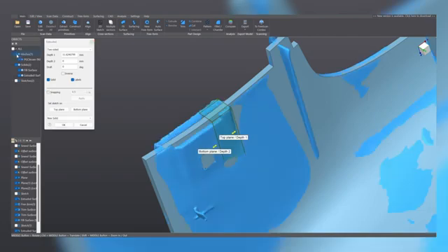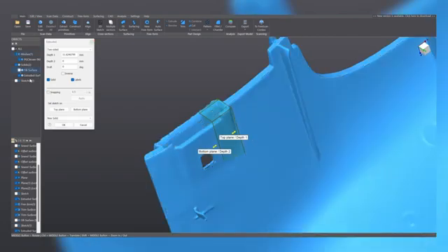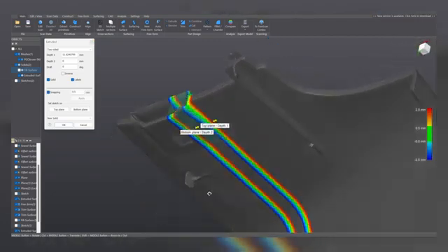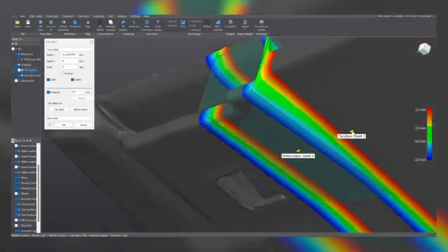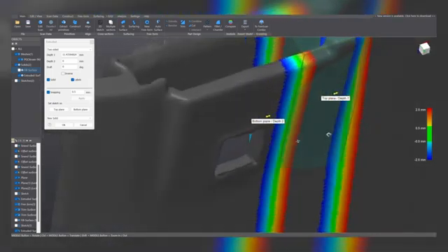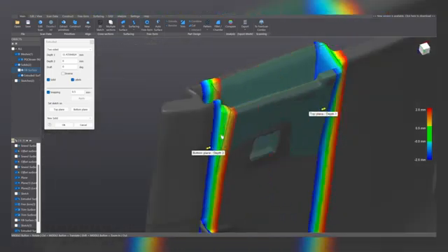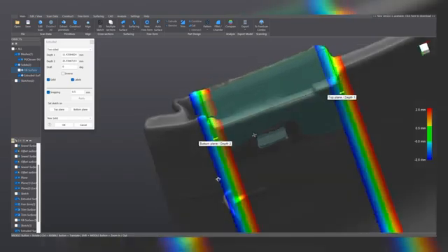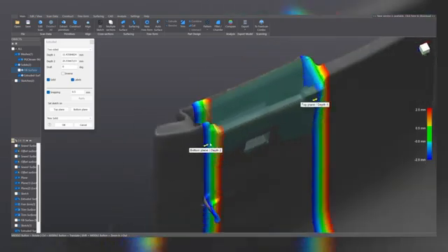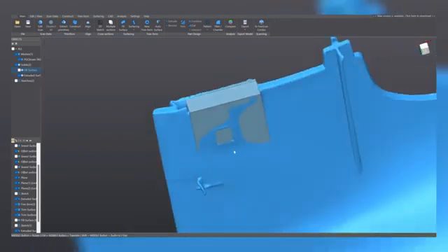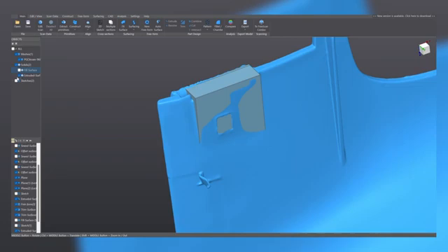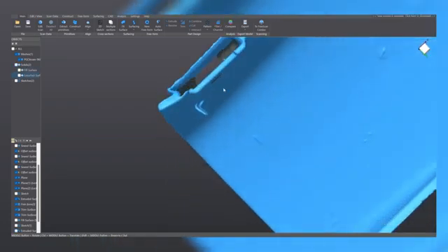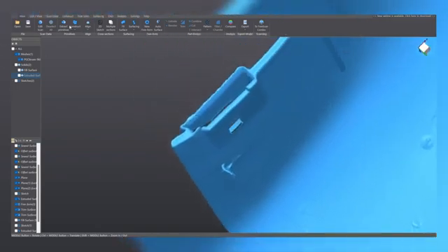Now, with the mesh displayed and the snapping tool on, we can select directly on the mesh what's the extension of this extrusion. And we are going to use these two walls here. Make sure that new solid is selected and click on OK. Now we have our basic solid, and we are going to tackle now the cuttings.